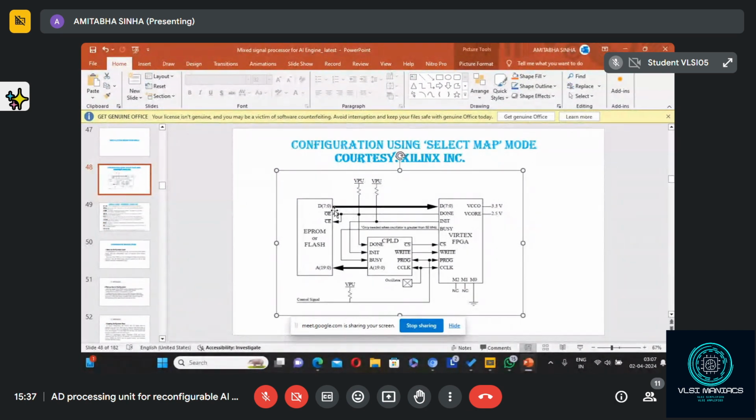When the data is being downloaded from the serial PROM to this, what will be the status of the done signal? Sir, the done signal will be 0. If the done signal is 0 and once it is over, good. And once it is over, done will be 1.